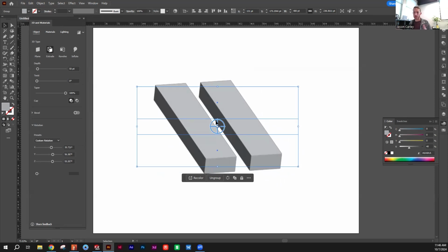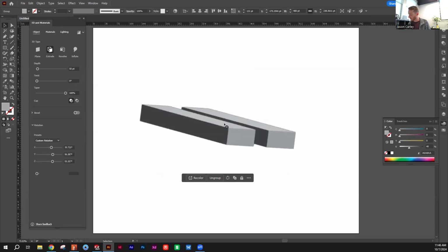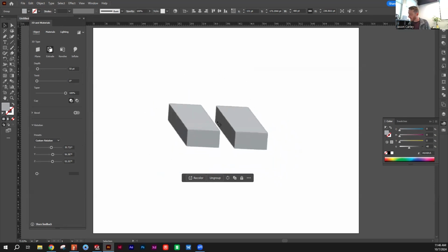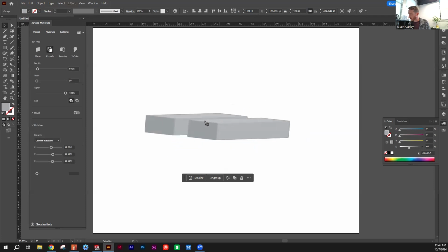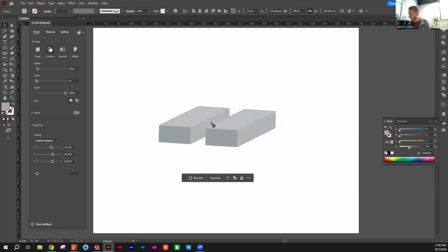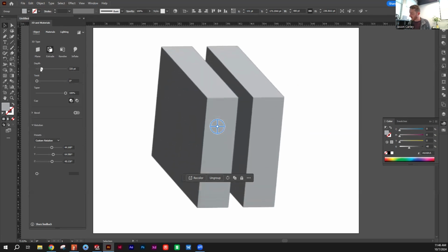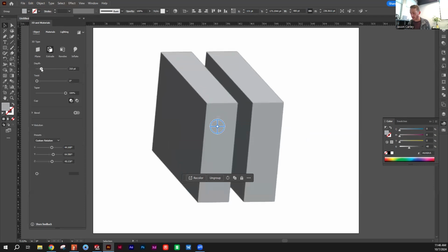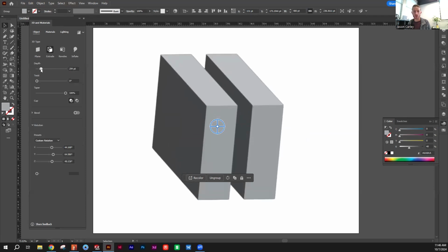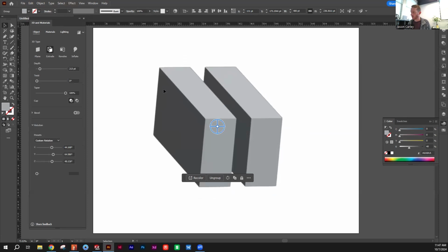If you have overlapping shapes, this might be really handy for grouping everything together to treat it like it is in the same environment. These two containers look like they might be next to each other, right? So I can rotate this into a useful position to use for an underlay. I don't know, maybe here. And there are some tools that show up in the toolbar over here. If you remember, we used extrude. By altering depth here, you can see what that does. This is, again, related to the points in my original coordinate system.